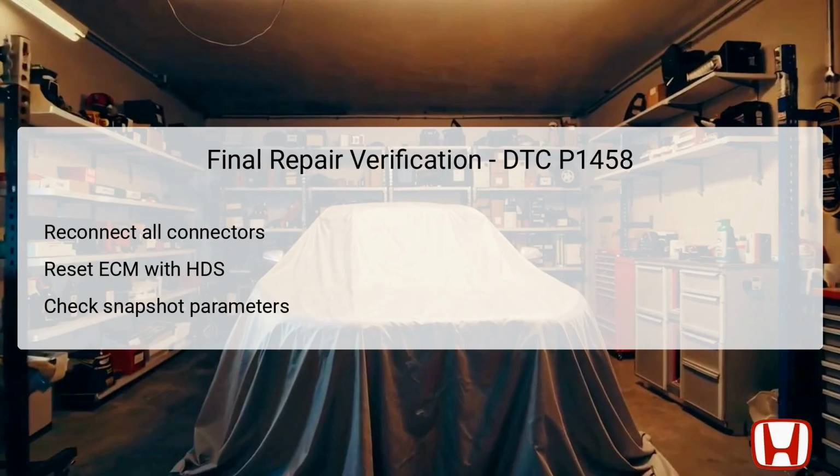If the difference between the maximum and minimum values remains about 0.67 kilopascals or less, it confirms that troubleshooting has been successful. If not, it will necessitate revisiting the diagnostic procedure and addressing any overlooked issues.